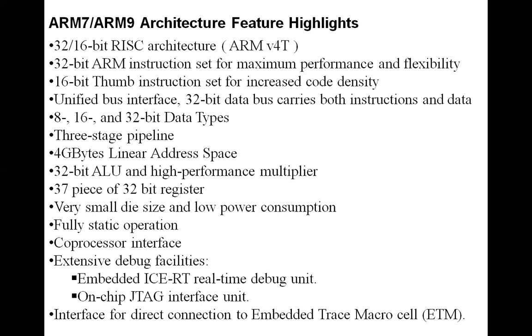Then the pipeline is one of the important features. This ARM7 has a 3-stage pipeline facility. This increases as you go to different versions, so you can find 5-stage and 6-stage pipelines also. ARM9, ARM10, or ARM11 will have extended pipelining features. We will see how the 3-stage pipeline works here.